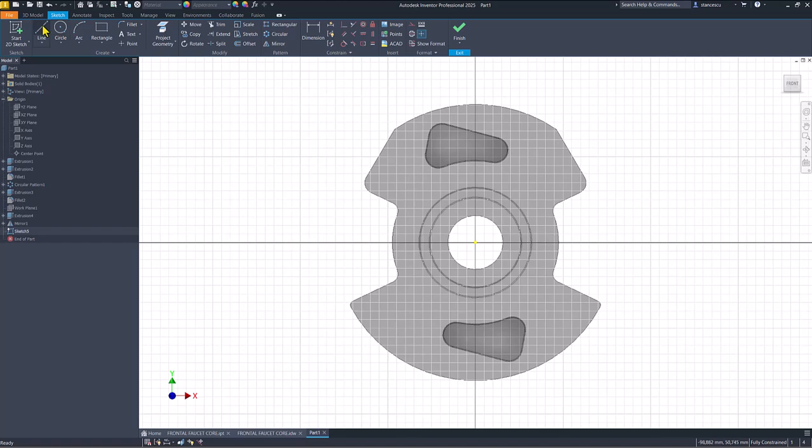I draw a line with a length of 26.5. Tab. I apply tab, and this means that I move the focus from the distance to the angle, and I write 45.